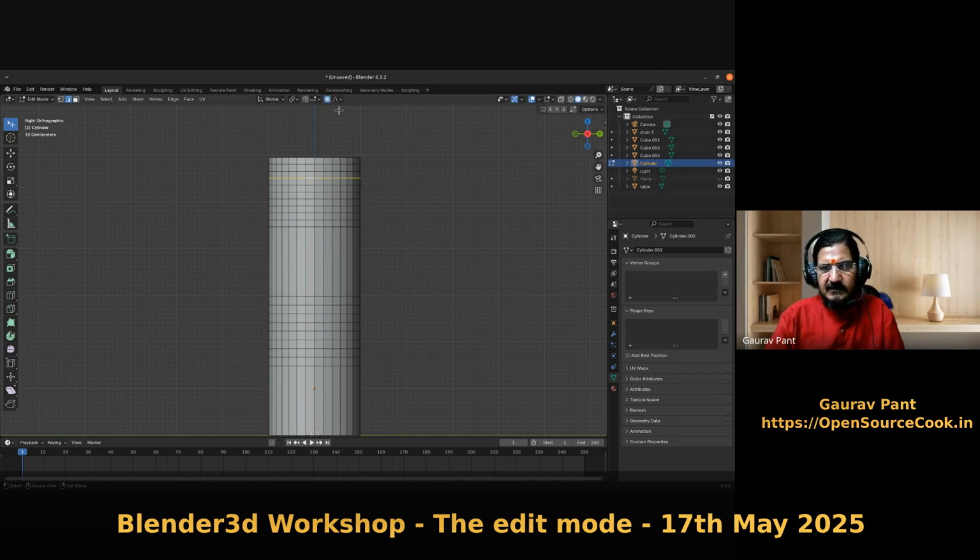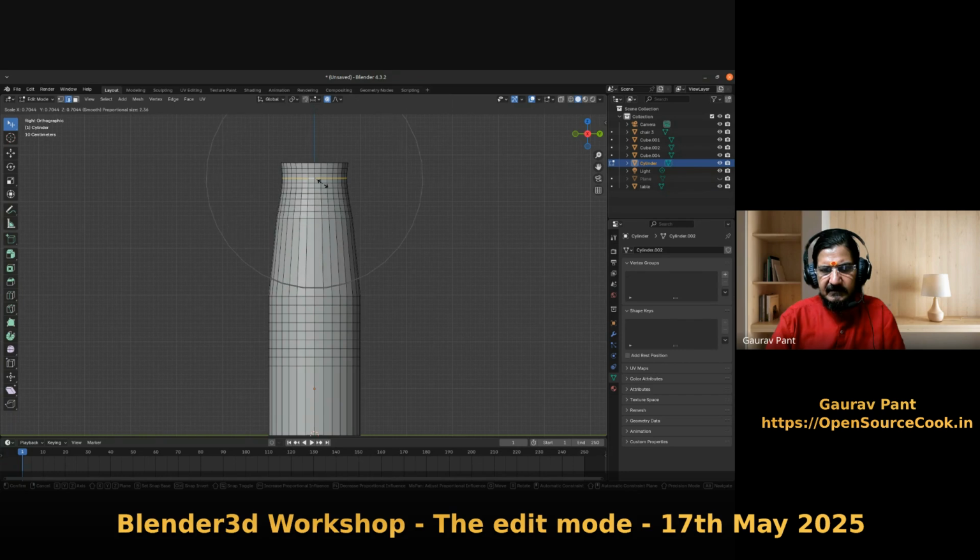If you turn on proportional editing, you will get these different shapes which we had seen in the loop cut part also. Now when I scale this, you will notice a circle coming up. This is the influence area. How much will be influenced? If I scale this, the remaining parts will be scaled accordingly. If I reduce this, the influence is reduced. If I increase this, the influence is getting increased.